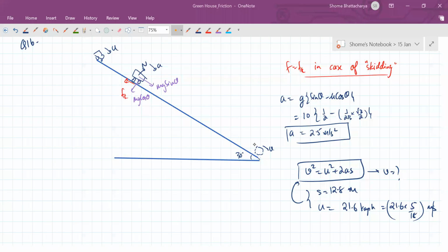No, in this case, the friction coefficient is not enough for retardation. Understanding the point, Krish? So in real life, the tire is designed in such a way with the material of rubber having a larger coefficient of friction. Only then it is possible to decelerate while going down the slope. For this kind of coefficient of friction, which is 1 by 2 root 3, it is probably 0.27 or something. So it's quite a less amount of friction.